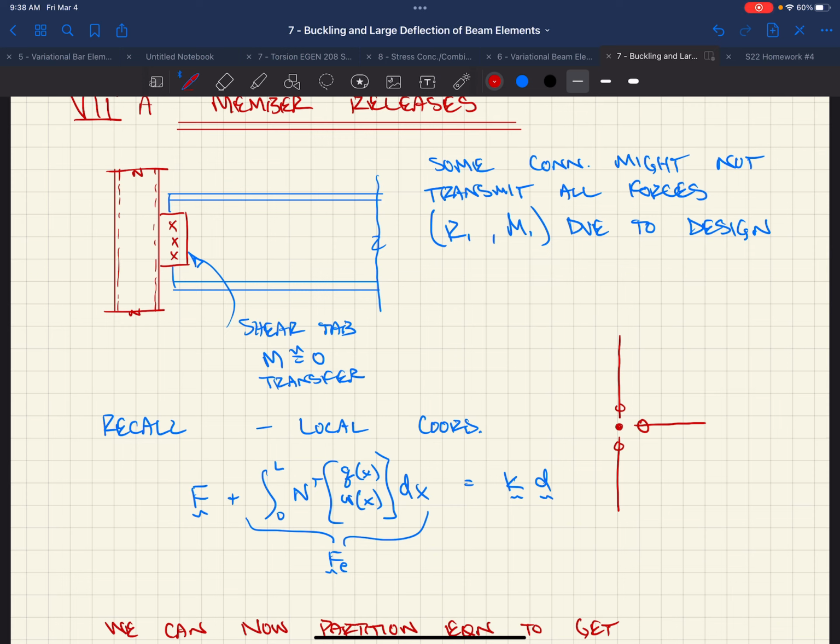So you have all of this going on everywhere. In some cases, if you had a steel gravity frame, a lot of times all your connections are released with respect to moment. You have shear tabs everywhere, and very simple base plate connections for your columns to your foundations, just a simple little 3/4 inch bolt, 4 bolts around the perimeter. You guys have seen those details. So you assume it's a pin, it can rotate, it takes gravity loads.